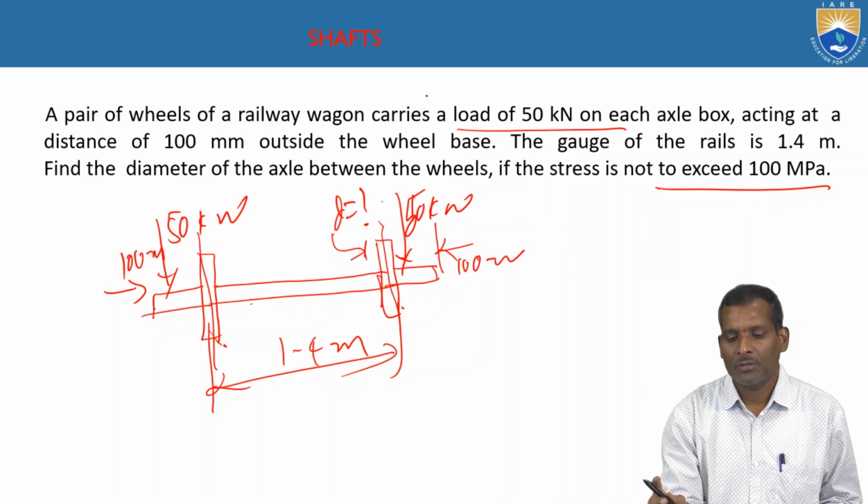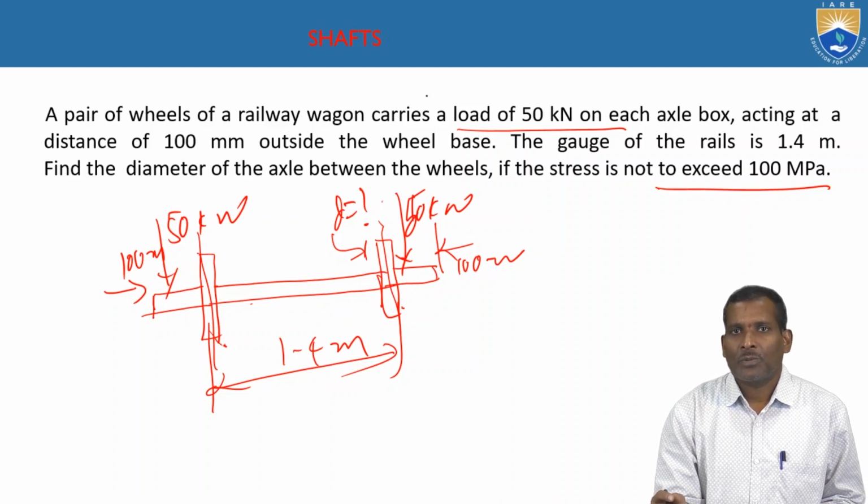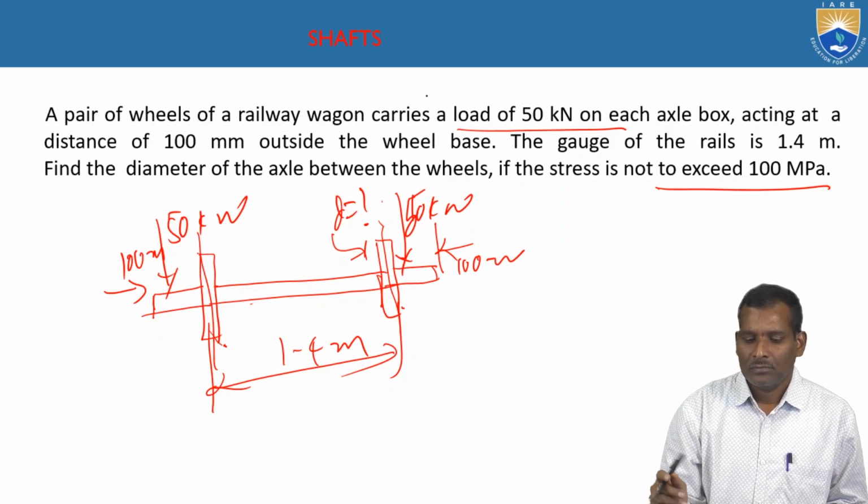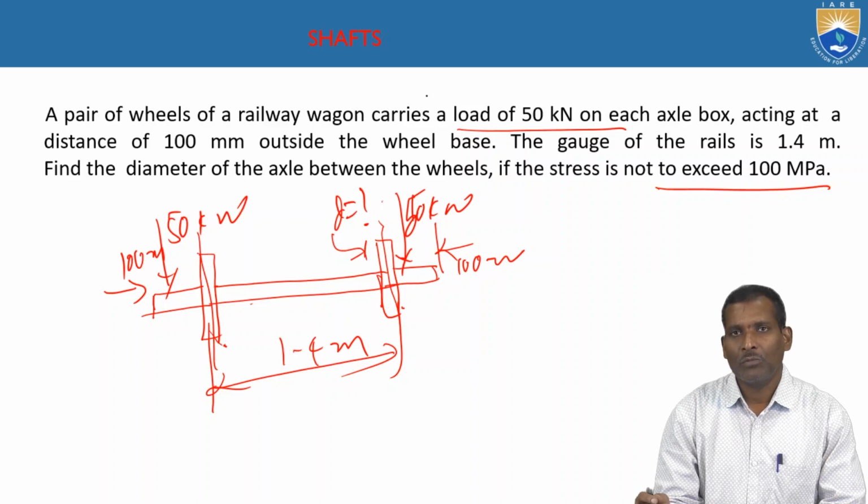For this problem, you have to calculate the bending moment, then apply the bending equation and finally calculate the diameter of the shaft.